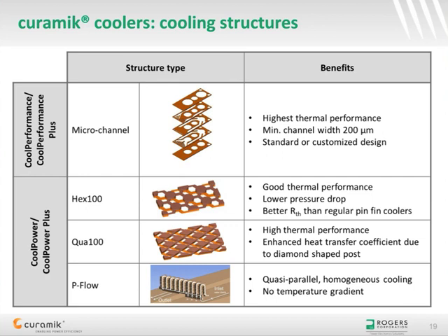First, Cool Performance and Cool Performance Plus products have been widely adopted in the laser industry in order to cool the laser diodes. In a stack height of less than 2 mm and with as few as 5 copper layers, these products achieve a very efficient cooling locally underneath the laser bar, as they enable heat flux up to 1000 watt per square centimeter.